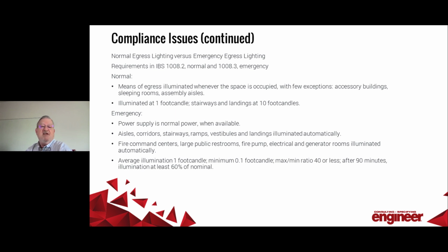Emergency egress lighting has to stay on for at least 90 minutes. And after that 90 minutes, the level can't be less than 60% of the initial requirements.